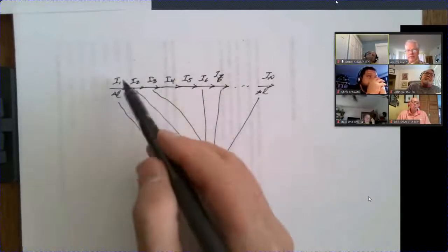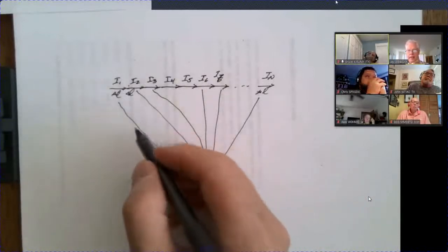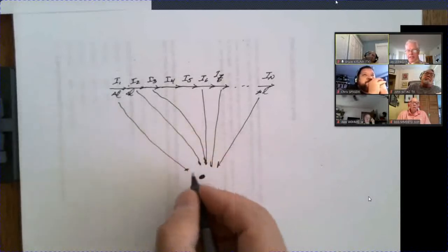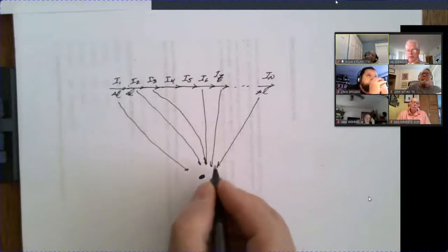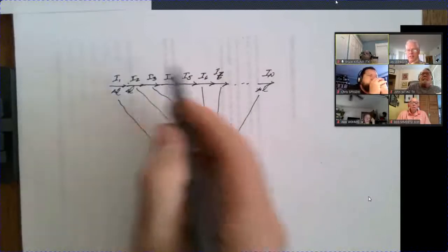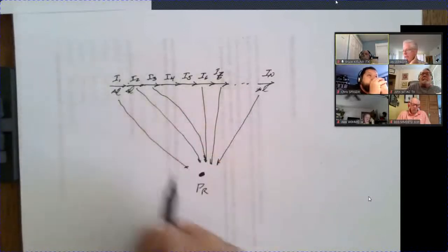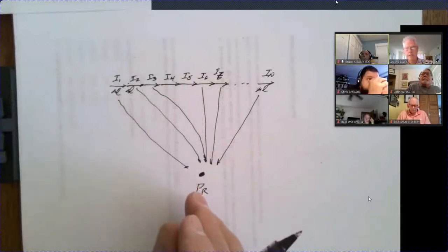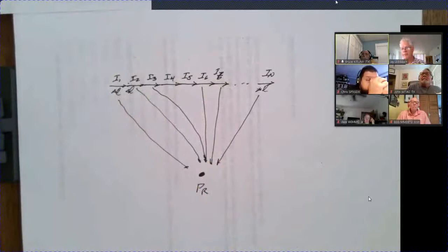It's not like, well, if this is putting out a quarter watt and this is a quarter watt and this is a quarter watt and so forth, you don't necessarily end up with the sum of all that power here. These fields will interfere with each other, and this produces an antenna pattern, which is also important. Where is your antenna putting out the most power?